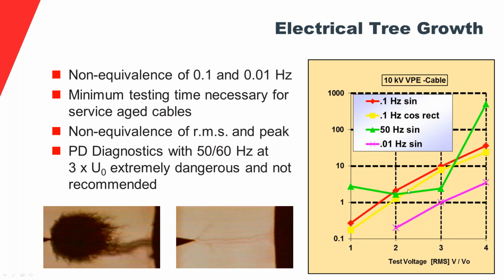But you can see the VLF is accelerating at 0.1 hertz. So this is why it's a valid test. If you take 1 hour, you can actually gain something by accelerating the failure mode, the electrical trees. Another thing that you can see, and I will elaborate on this a little bit later: if you reduce the frequency, which IEC doesn't allow based on scientific publications, but IEEE does, because that was some of the manufacturers' requirements when the IEEE standard was made,